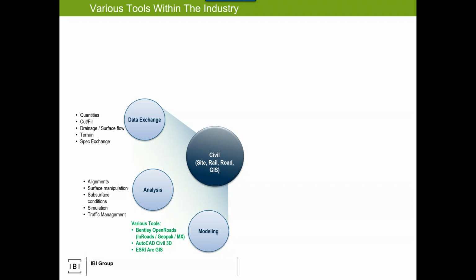If you're familiar with the push and pull of coordinates, I could have my site in Civil 3D. I publish the coordinates of my site. I go into Revit. I pull those coordinates in, define my location, and then I share my coordinates, and away I go. It's shared across all the Revit models, and then there's this push and pull. At least the coordinates are shared, and you can make things work.